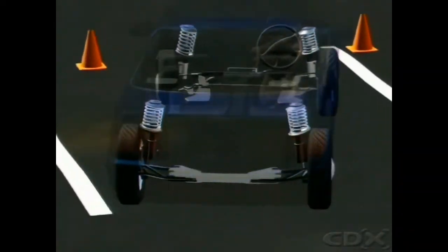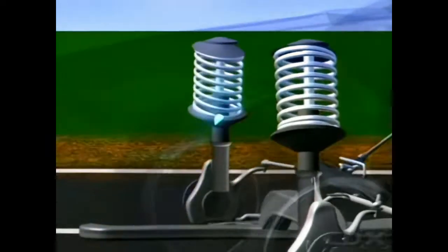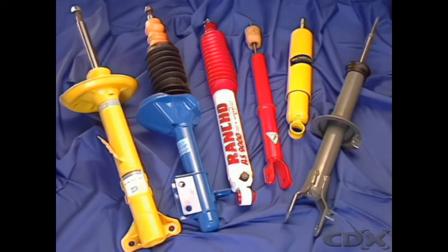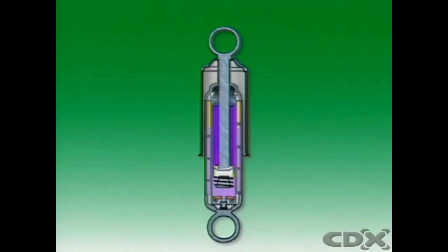Shock absorbers have a marked effect on how well tires follow a road surface. They damp the natural bounce over the road and reduce spring oscillations. There are different kinds of shock absorbers, but they all use a piston sliding in a cylinder filled with oil.